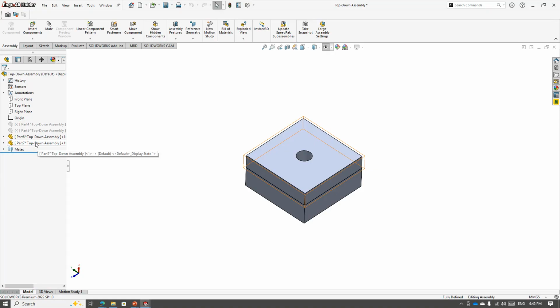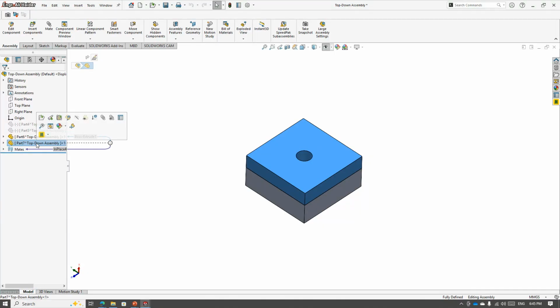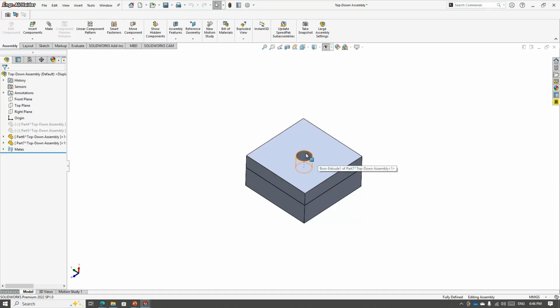But at the same time you notice the error, right? And when I come back into the assembly, I saw the error in the second part. And this is very simple, and it took me very little time to guess what the issue was, and I resolved it. But for example, if it is a very huge assembly with hundreds and two hundreds of parts, and each depends on the reference part, and you made some accidental change to the main part, all the components will get some error. And you will be blown away by how this happens. You will try to press Control Z to avoid that. So the top down assembly approach can cause this issue.